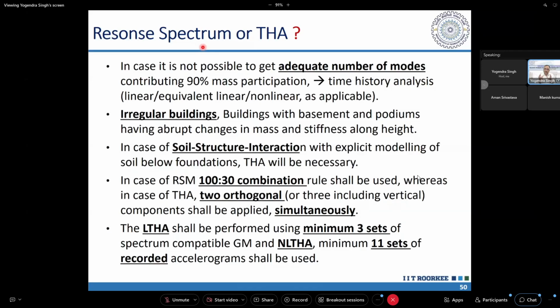The well being very rigid, it will not be accepted, and that will move more or less rigidly with the soil. So that's why on the well, I have to consider the additional forces, and those forces I can consider simply as M into Z. So what I can do is make a model of the bridge by fixing the pier at the top of the well, and then the inertia force acting on the well, I can calculate separately, and that I can apply as static force on the well.